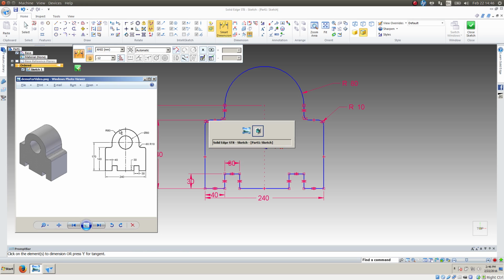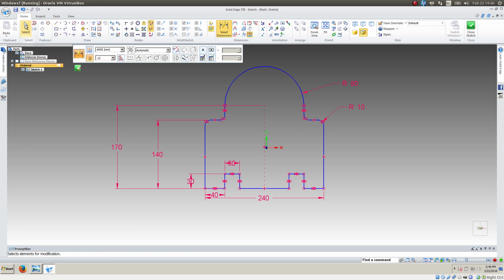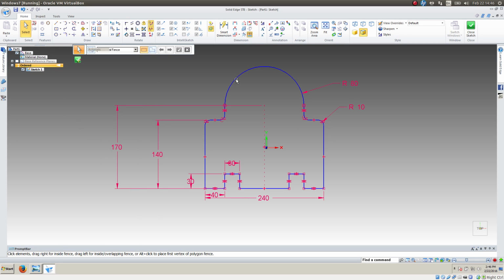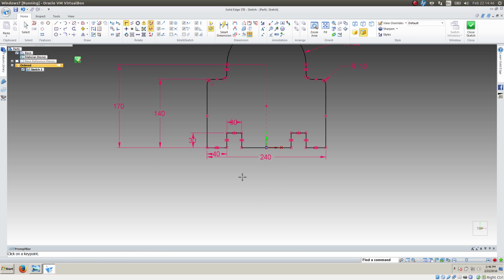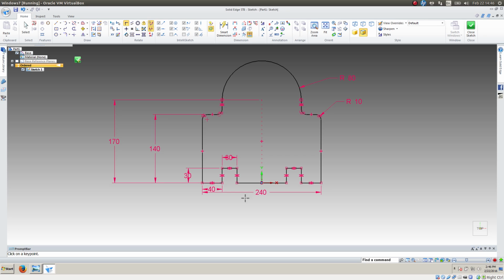Okay, so that might be most everything with the outside of the shape. Let me see. I grab stuff and drag it around, and nothing looks like it's changing with the profile, but it's still moving. So that means that none of these lines are going to change relative to each other, but they're changing in space. So their positions are changing in space. So I use the connect constraint to connect this midpoint to the end of that line.